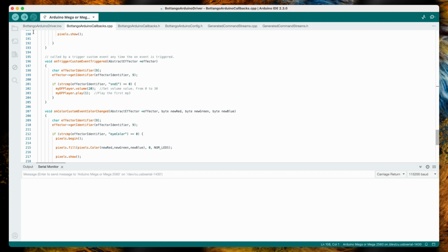So let's pause a bit here and talk about the DFPlayer and the sound files on the DFPlayer. I can only highly recommend you to search for the instructions for the DFPlayer and how to put the sound files on it. For some reason it doesn't use a proper file system with naming, but it orders the files in the sequence they get copied onto the SD card. And they also require a naming convention: 4 digits and then .mp3 or .wav.